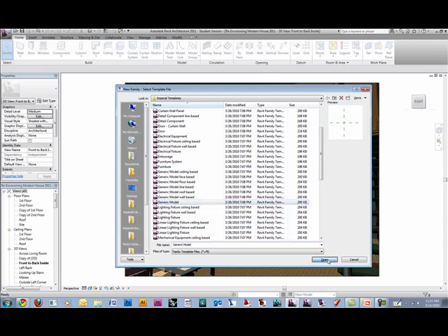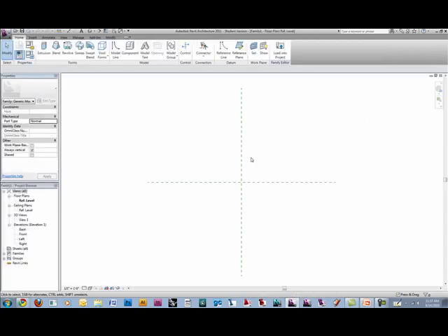It's more important to see about the wall-based and the ceiling-based, because if you create a ceiling-based family, there's no way to place it unless you have a ceiling in your project. Or if it's floor-based, you can't place it unless you have a floor. So if you're not really sure exactly where it's going to be going in your project, then you don't want to make it so it can only be placed on a certain wall or face, unless you know it's a wall-based component. So pay attention to those before you start making a family.